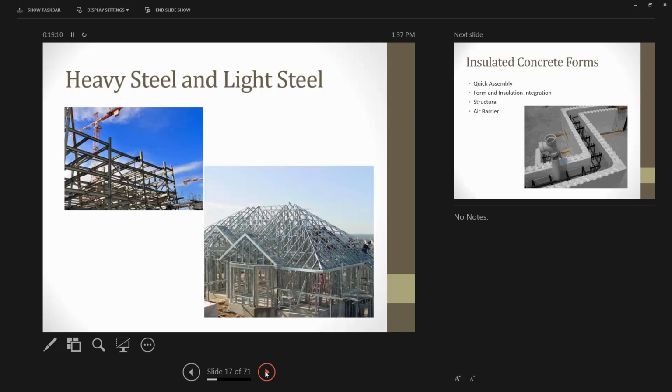While it's always a good idea to create a thermal break and separate the wood from the outside, by code you don't have to. You will have to with the steel, especially in a colder climate.